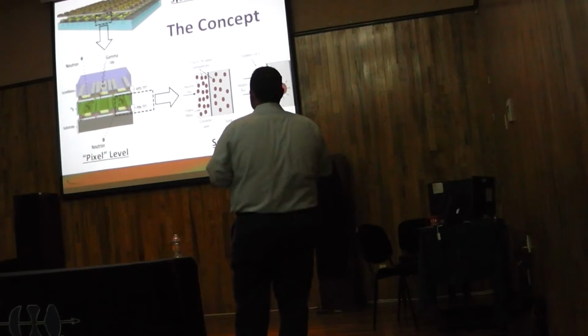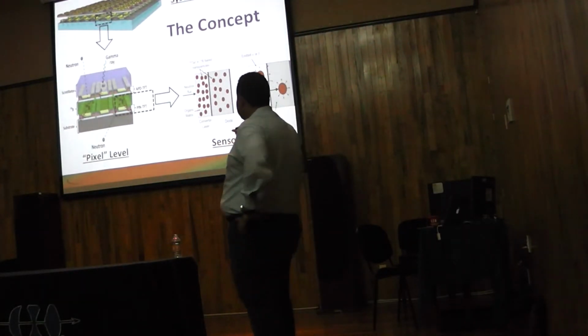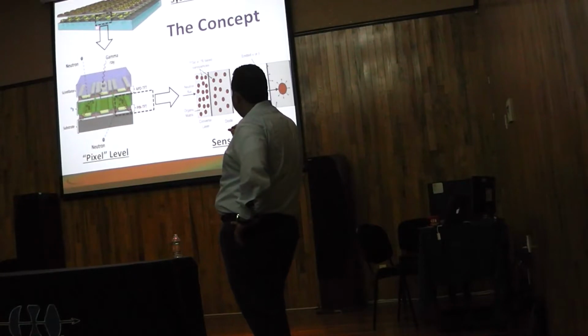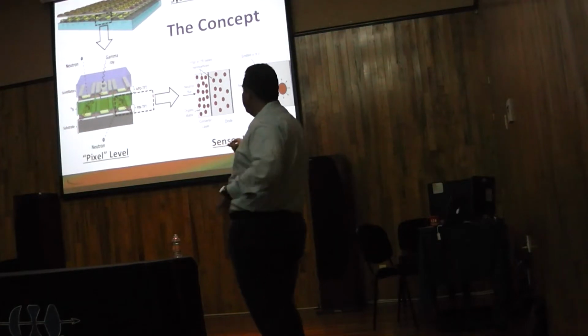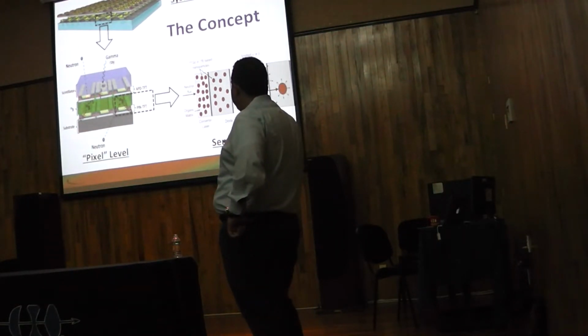That is a very simple concept. The way that we're doing it is different in the sense that we have our substrate, these are our sensors here, and these are our circuits. If we look closely here, what we have in the substrate, then we have PIN sensors in the bottom. Then we have this boron 10, which I'll explain a little bit later, which is a converting layer for neutrons. We have avalanche photodiode, which is the sensor for photons coming from the scintillator.